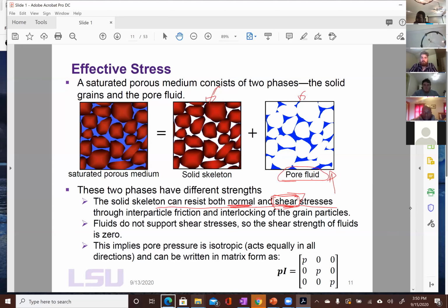And the reason, how is this porous material able to support stress? You try to shear it this way, meaning you fix an object on the surface and you try to pull it this way. What happens to the grains? They start to interlock and you have frictional resistance. That's how an object is able to support shear stresses, but you can't have that with water, right? It just shears continuously. Same with pliable shale, weak and unconsolidated. So you slide it up, the grains just continue to deform continuously. And that's the important point there.